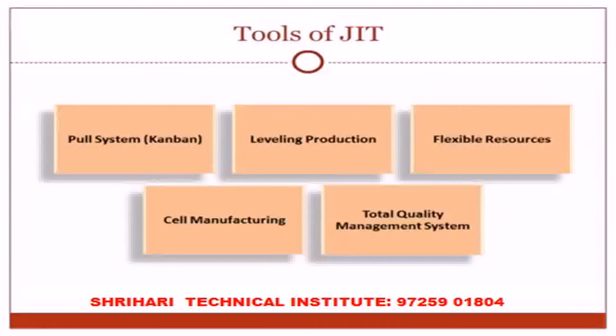Cell manufacturing deals with the arrangement of work centers and equipment layout, as well as the facility layout. An efficient and popular layout is the U-shape, with a worker in the center with parts, tools, and machinery within reaching distance. TQM systems, quality systems, provide structure and control to processes. Documented processes, effective training programs, continuous improvement activities, and audits allow a system to be monitored, measured, and improved.